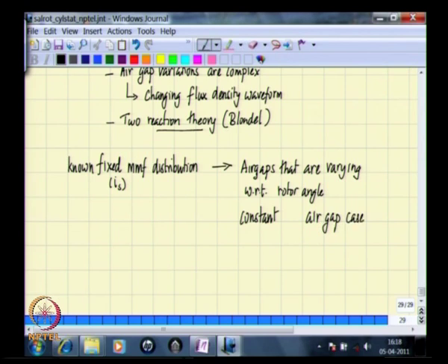It is not a single air gap now, but the machine then has two constant air gaps, and across these air gaps there is an MMF applied, so to say a component MMF of the original MMF, a component MMF applied that varies with rotor position.